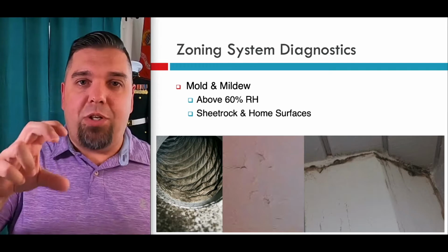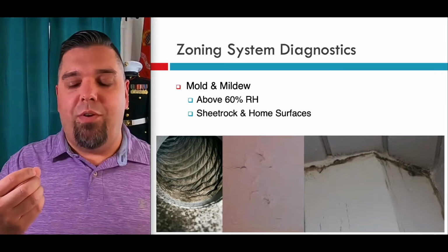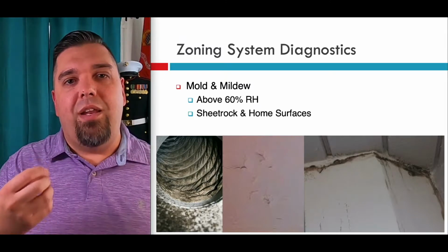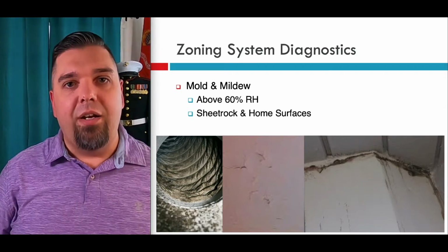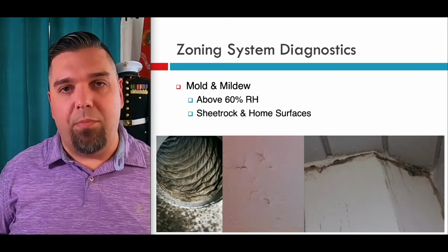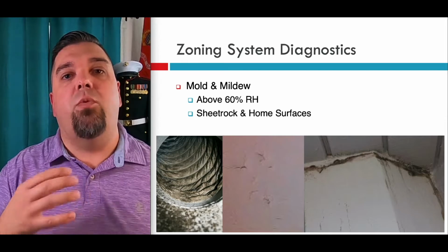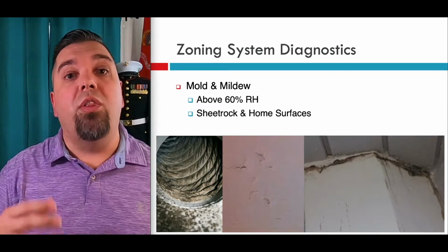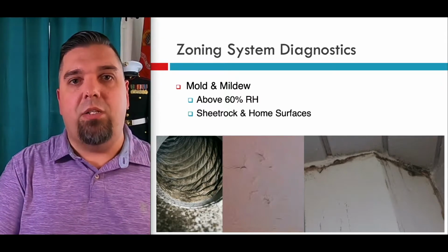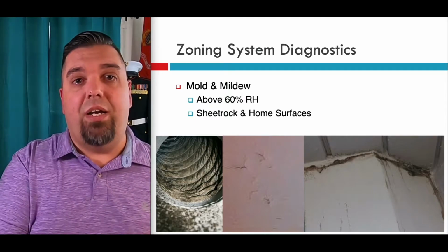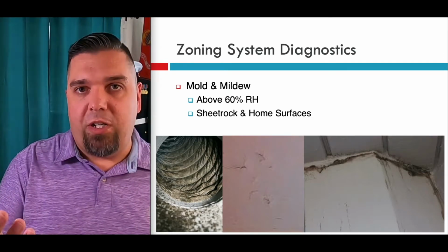So that's why people keep turning it down, and then you start to reduce the dew point of the air, right? And if the device that you have, let's say your ductwork, is below the dew point of the air, that's when we get condensation, and that's when mold and mildew starts to grow, all right? So that's why the target is really important, I think, for you guys to understand why, so you can explain it to a homeowner on the front end during the sales process, right? Why you're not comfortable because it's 60% relative humidity in your space, and the system needs to be redesigned, or why zoning isn't gonna fix the problem, and why we need a whole house dehumidifier, for example, okay?